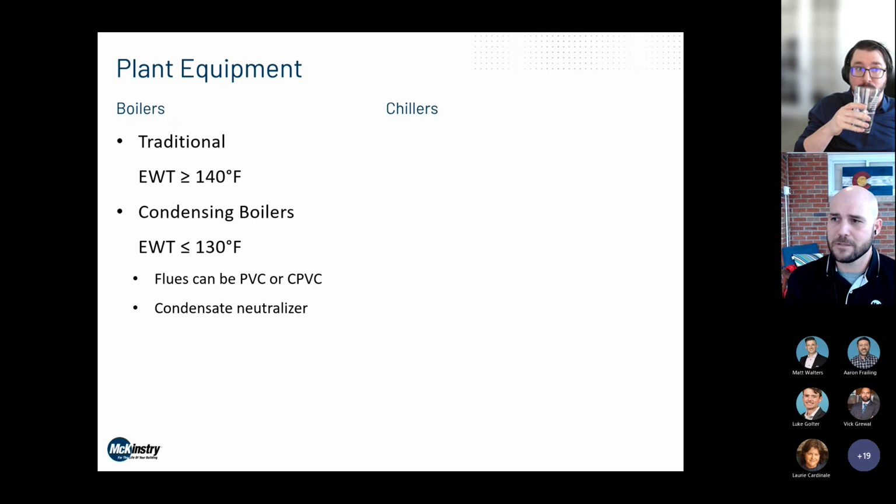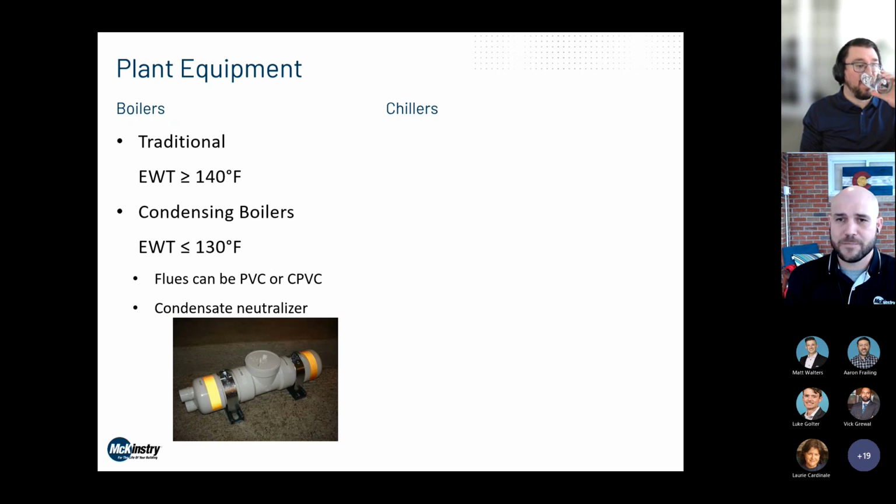Actually, pure water is slightly acidic. Distilled water is as well. And so it runs through a condensate neutralizer, which can often look like just a stick of PVC plastic, and the neutralizing agent is oftentimes chips or flakes of limestone or any kind of lime, something that's basic. It'll move slowly through that, and with just enough dwell time, its pH will get to 7, it'll neutralize and then pass through and can just go down the drain without harming any metal pipes.